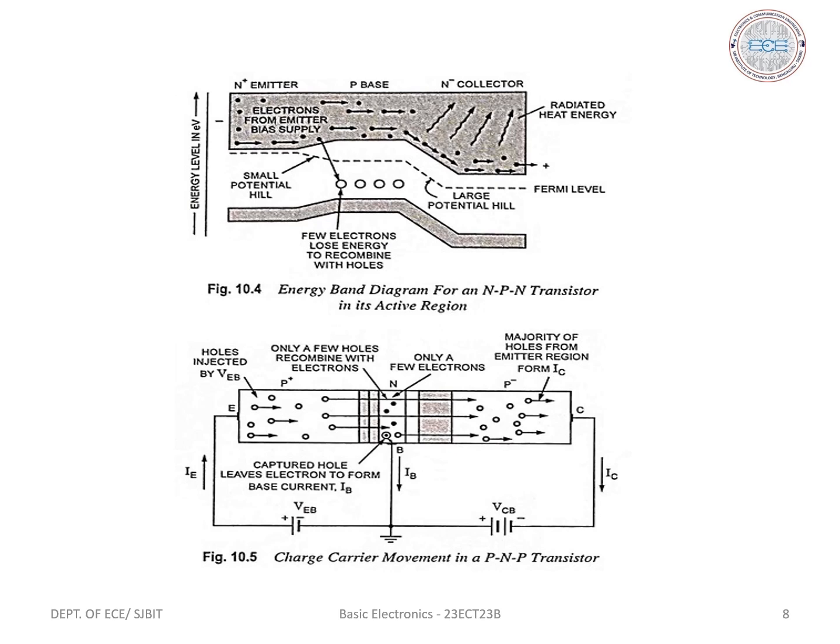In the lightly doped base, there are few electrons available for recombination. Therefore, about 2% of the total emitted holes will flow out via the base terminal and the remaining are drawn across the collector by the electric field at the reverse biased collector junction. As in the case of the NPN transistor, the forward bias at the base emitter junction controls the collector and the emitter current.